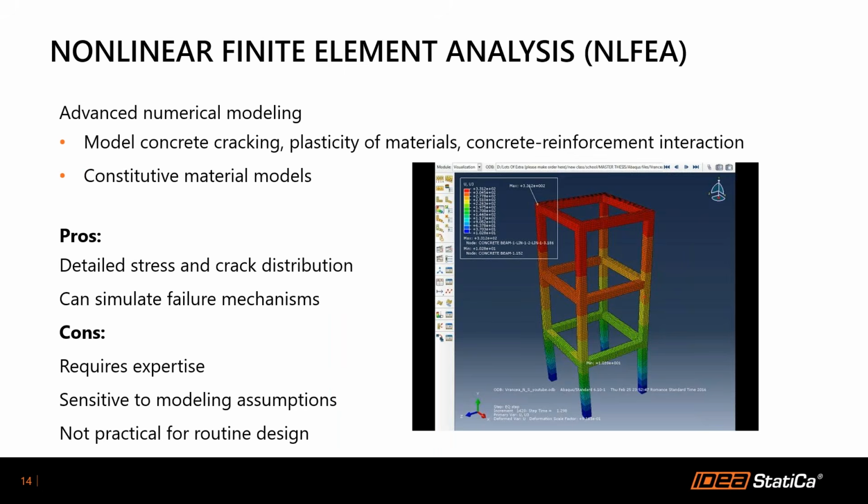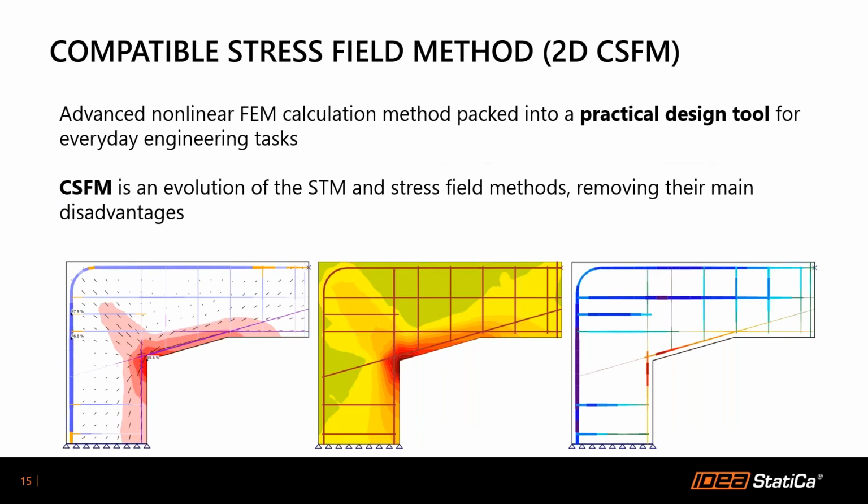simulate failure mechanisms. However, the main disadvantage is that it requires a lot of expertise, and it is really sensitive to modeling assumptions, so it is not really practical for routine design in engineers' everyday work. We came up with a third approach. The method is called the compatible stress field method, or CSFM. This is an advanced nonlinear finite element calculation, which was packed into a practical design tool for everyday engineering tasks.